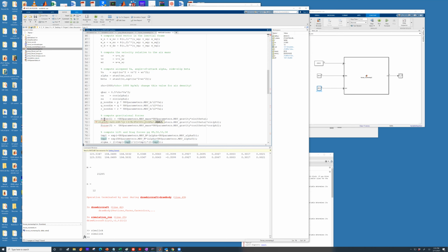It tells you that code generation requires variable force to be fully defined, which means the data structure should be completely known. So here is what I'm going to do. Rather than defining force as an element of a vector, I'm going to define it as a scalar variable. What do I mean by that?